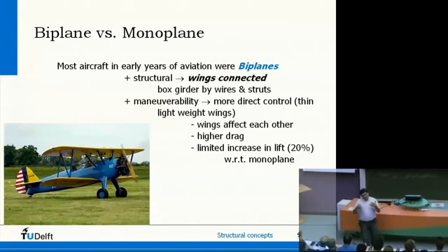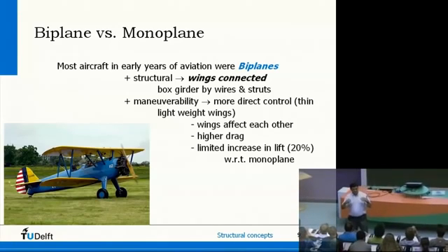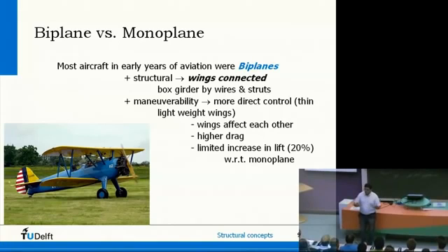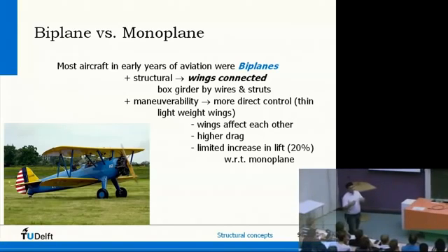So the strength is related to the maximum load a specific structure or material can take. And the stiffness is how far it deforms during a certain load. If I have a very little deformation with a particular load, then I can tell, okay, this is a very stiff, a very rigid material. If I have a very large deformation with the same load, then the material is flexible, it's very unstiff. Yeah. That's the difference between strength and stiffness.